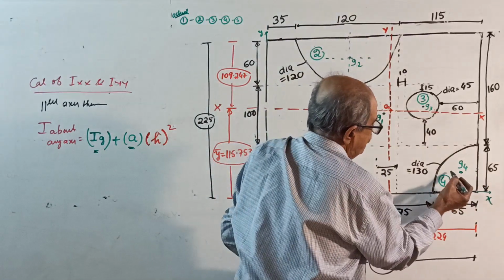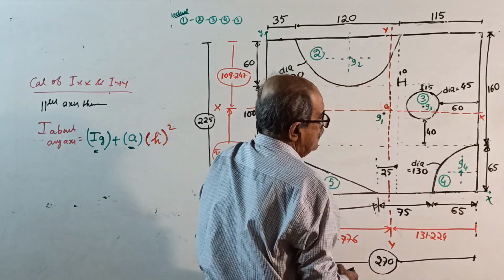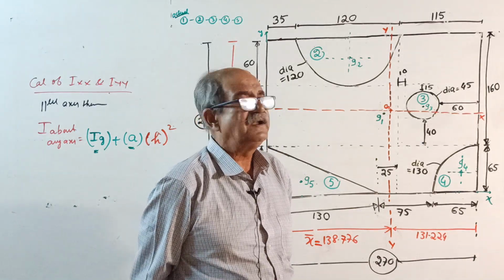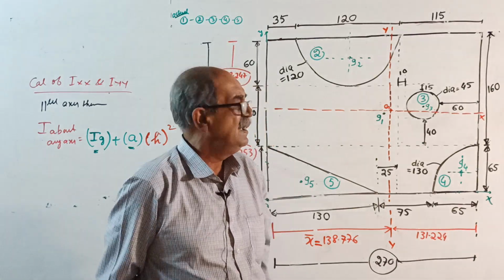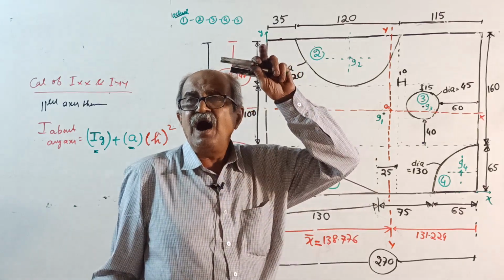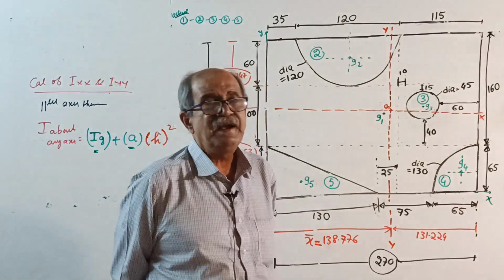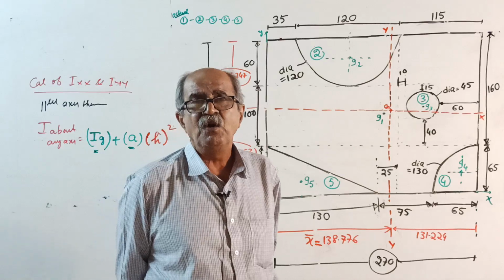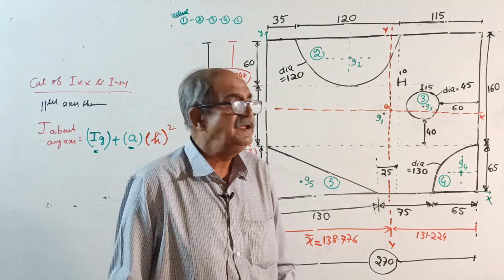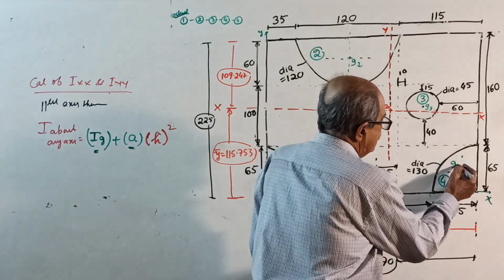And here, your one axis will come here, Ig, one more Ig will come here. When you write that Ig, there is no symmetry for quadrant. So quadrant symmetry is not there. About both the axes, moment of inertia is half of the semicircle when symmetry is not there. When symmetry is not there, for semicircle it is 0.00686. So its half is 0.00343, 0.00343 into d power 4.